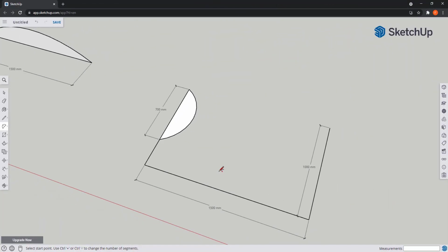Now look at the next example. This time I want to add the same 2-point arc, but on the other side. First I click in the first point, then, as I cannot snap the second point, you can see that if I drag the pointer along the edge, I type 700 and I can make the second point start from there. Finally, I just need to specify the bulge.